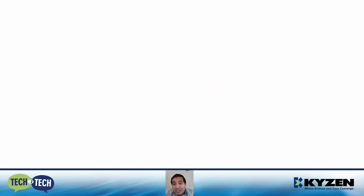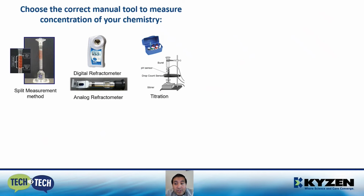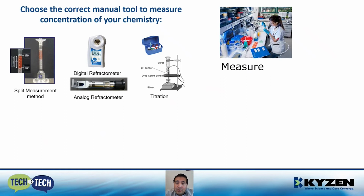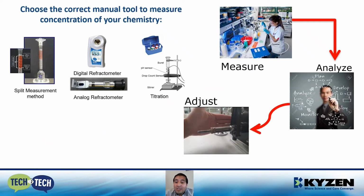Since the concentration percentage would still have a variation using the controller, either up or down, you will still require to monitor the concentration percentage of your process on a regular basis by using any of the recommended methods described in previous tech-to-tech sessions, to measure the concentration, then analyze the data readings to find deviations and trends, and readjust the controller setup accordingly. This is a never ending loop that repeats along the time in order to keep your process under control.